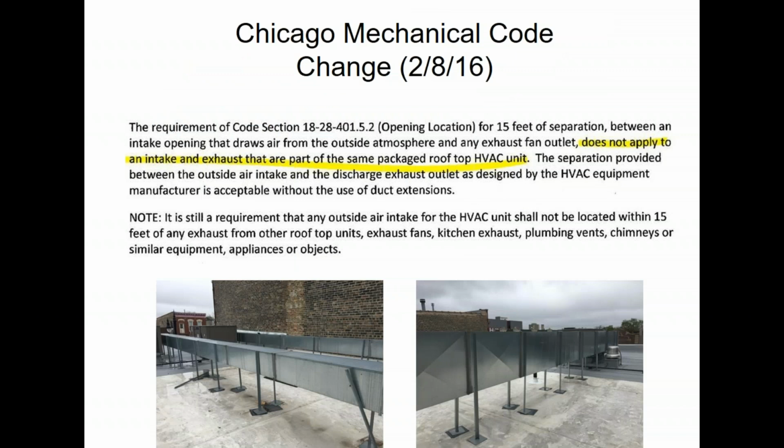Unrelated to the energy code, I just want to point this out while we're on economizers because I still keep getting this question. The city of Chicago proper used to require the outside air intake of a packaged rooftop unit to have 15 feet of duct added to it to keep it away from all sources of exhaust systems. That requirement is still in effect. However, there is a new exception to that. By new, I mean 2 years ago.